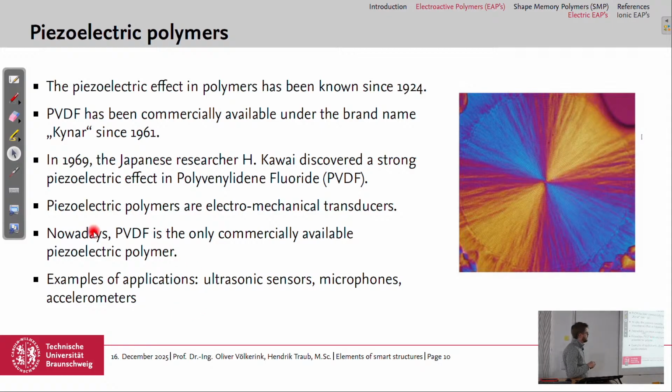And PVDF is also the material we used in this multifunctional bond line I had in the first lecture for the crack stopping. So PVDF gives some improvement to the mechanical performance in this adhesive bond line due to its crack stopping features, a toughening of the material. And the original idea was to use this piezoelectric effect to sense also the adhesive bond line. But it didn't work out, so we integrated microstructures into the PVDF to use them as strain gauges, and we will later on see why it didn't work out to use the piezoelectric effect of the PVDFs in the multifunctional bond line.